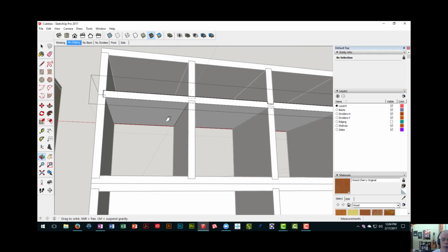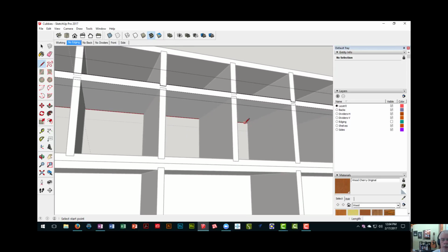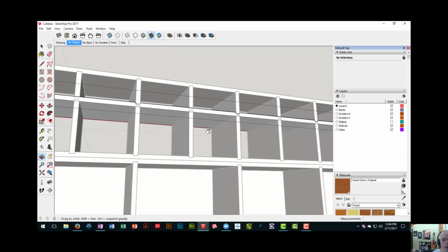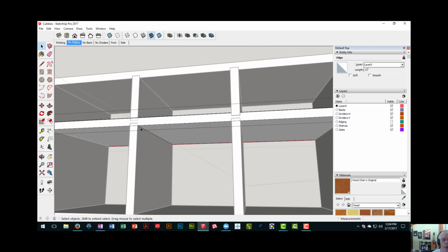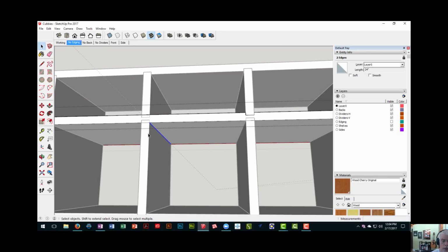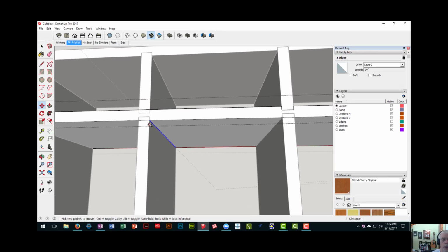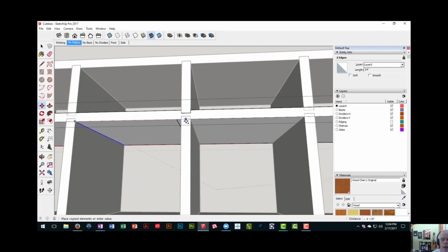But the point is, I want to move those 2 lines, or copies of those 2 lines, to each of these vertical shelf positions. So what I'm going to do is click on this line, shift click on it, so now I've got both lines selected, and I can actually copy lines. So I hit M for move, Control for copy, and since I have these shelves in place, I can see exactly where I want to move it to.